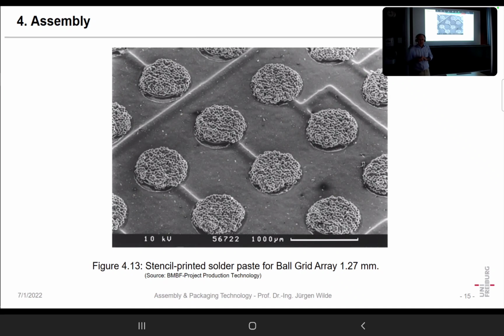And the second thing is also important. If you have 400 IOs on a periphery, you must get the signals somewhere, and bringing 400 IOs away in all directions, you can even do that on one layer of your board.